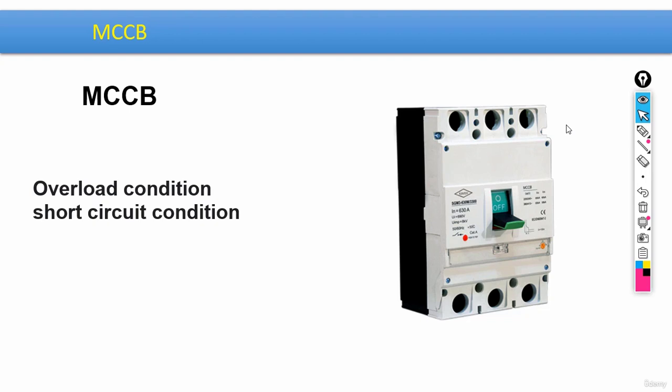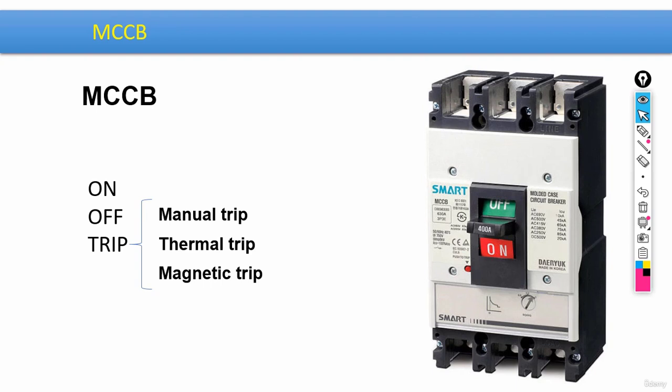Well, to be honest, they work kind of the same, but the difference is that MCCB breaker supports a very high electrical current. And compared to MCB breakers, this one actually has some additional sub-items, you can say. Well, as for the similarities with MCB, this one also protects the circuits against overloading and short circuits. Alright, now let's talk about this breaker in more detail.